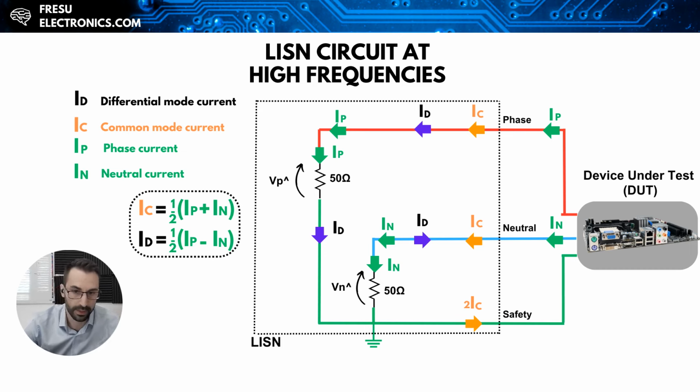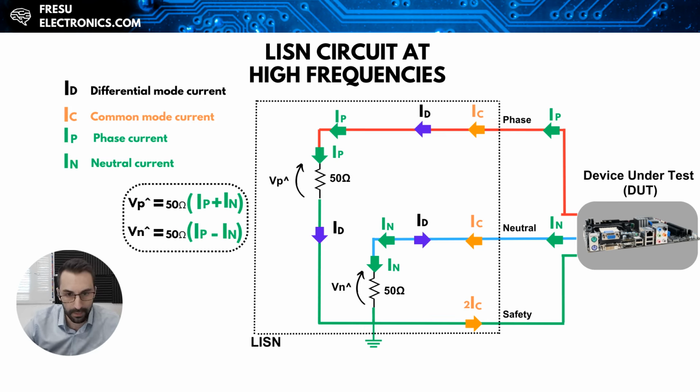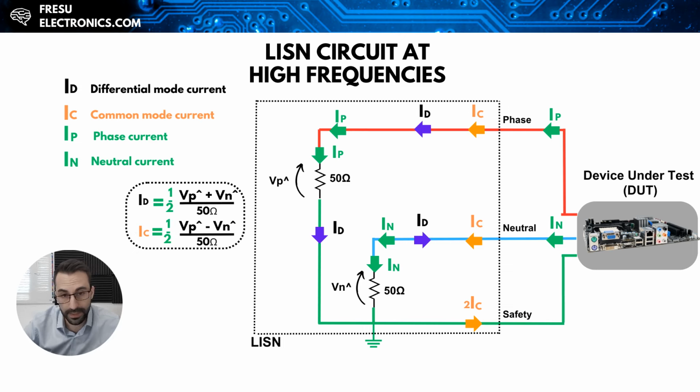So now we can rewrite the voltages VP' and VN' in terms of the phase and the neutral current, remembering also the relationship they have with the differential and common mode currents. And this means that by measuring the voltages across these 50 ohm resistors with the spectrum analyzer, we can find the differential and the common mode currents.